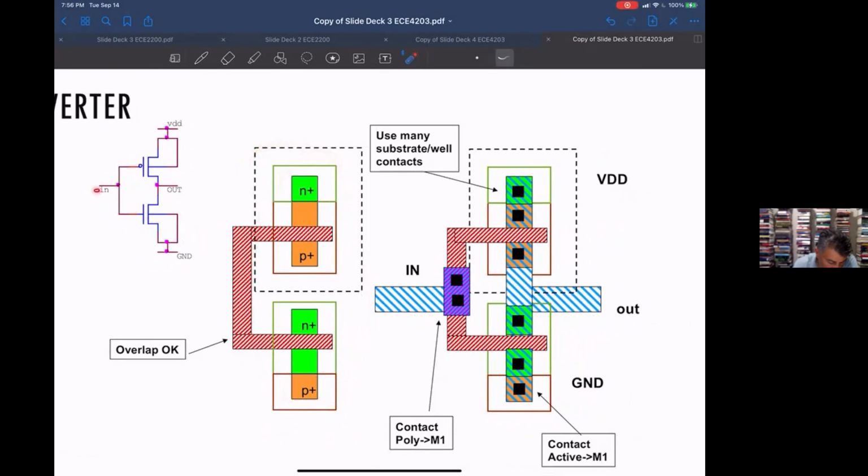And then once you want to make the connectivity to this, you go to metal lines. So you have a metal 1 here. There's a contact between metal 1 and poly. So these are these black boxes. And then I have an output, also basically metal 1.